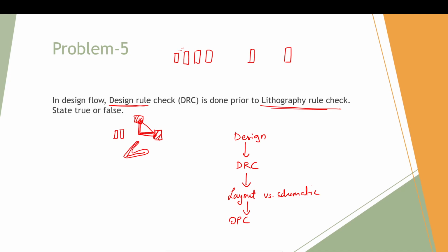So the proximity is different for this and for these. Based on the proximity, the exposure might be different, so that will give a different yield at different places. Here, for the light to pass this mask, because all the designs are close to each other, the optical field that it sees at the wafer might be something like this, whereas here it will be higher. So the proximity effects might come in, so you need to simulate for all these things.